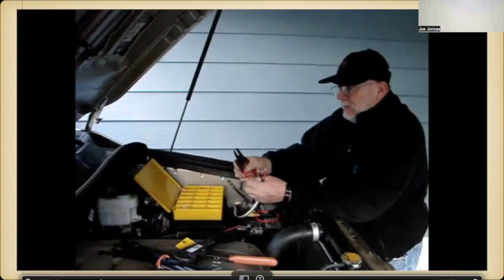If it were standard automotive cable, which is okay to use, but standard automotive cable has an outside jacket on it, and it's usually gray. And the copper, the wire is just copper. It's not tin. So when you put copper with tin, those are dissimilar metals, and they can corrode.